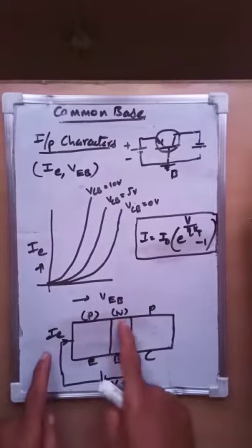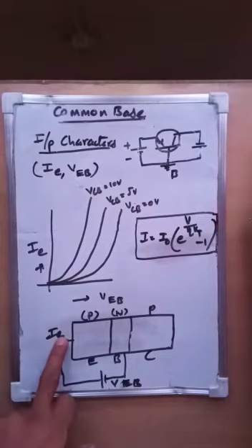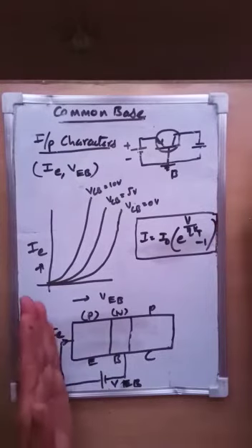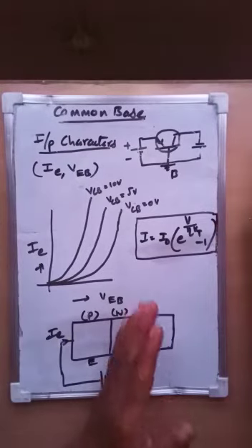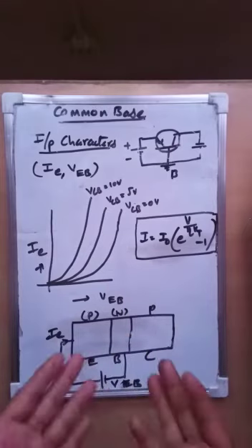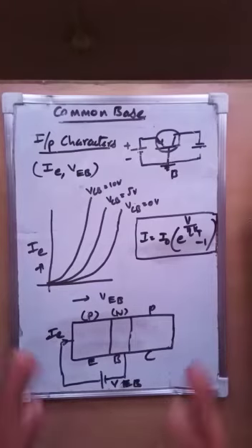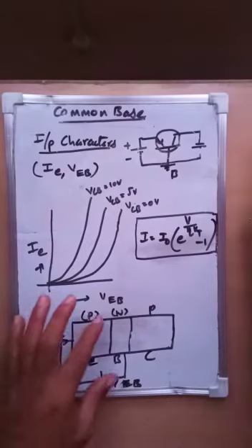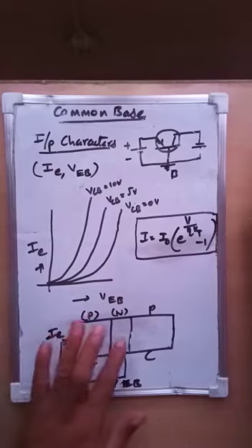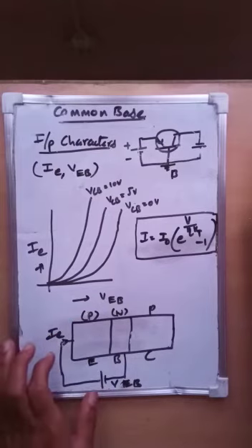If it is an NPN and we need forward bias, we have to give negative voltage to the N emitter, so that more electrons go into the base, where the base is P-type and the collector is N-type. Whether it is a PNP or NPN transistor, the principle of operation is the same. Majority carriers enter the base region by forward biasing the emitter.